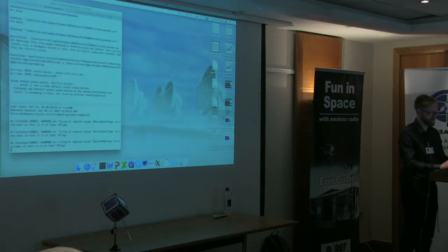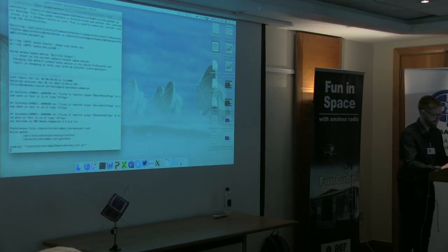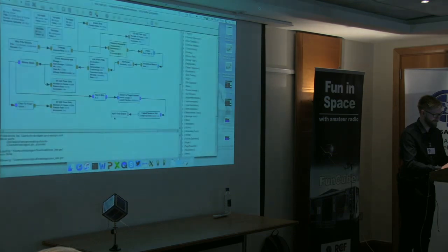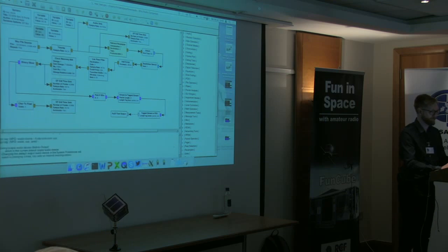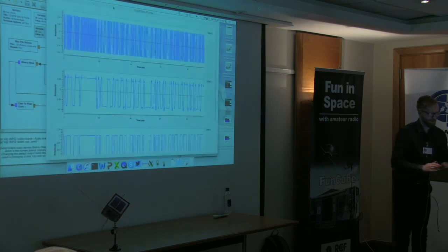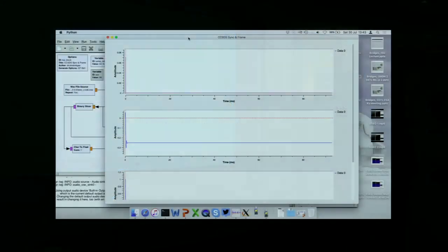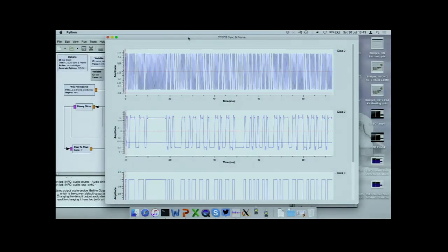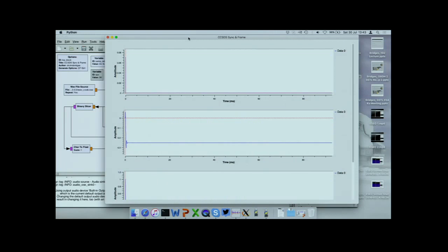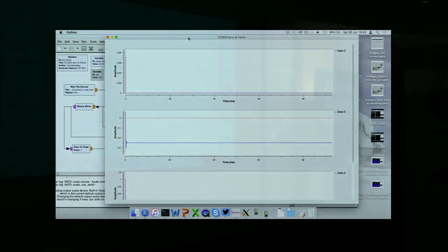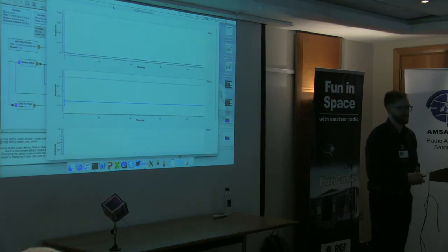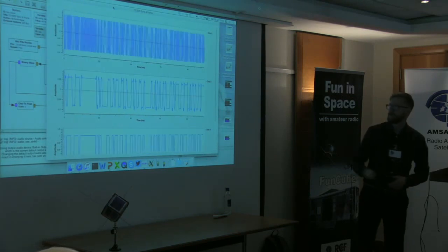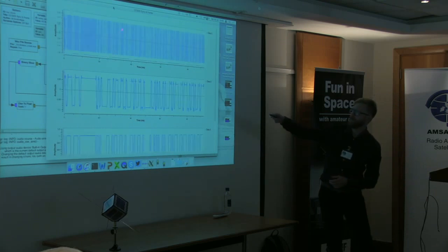So I'm going to run GNU Radio Companion again. That will load. Excellent. And then I can hit play. I've already got my flow graph. You can see what I'm doing there is replaying just a wave file over and over again in that flow graph. There's a setting just here which says repeat equals yes. Obviously if that wasn't there, it would just be a very, very tiny wave and just go blub, and then that'll be it. And we're converting our audio wave.